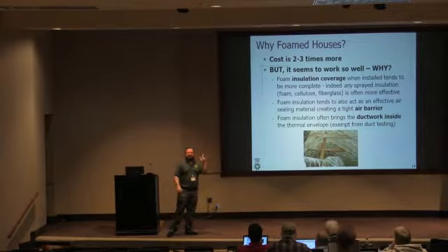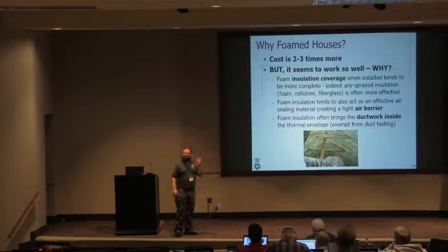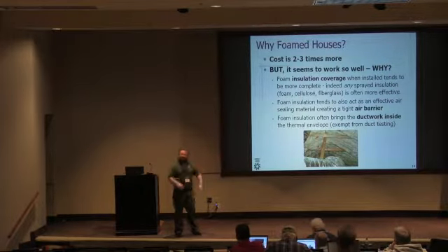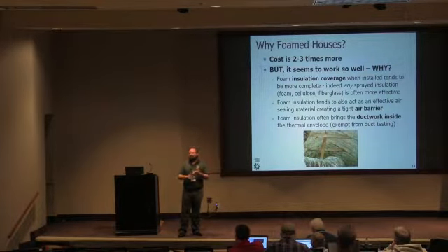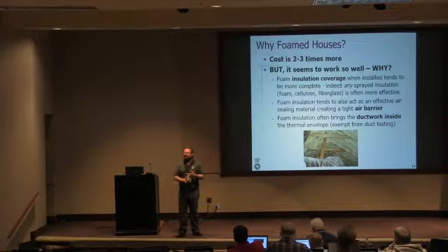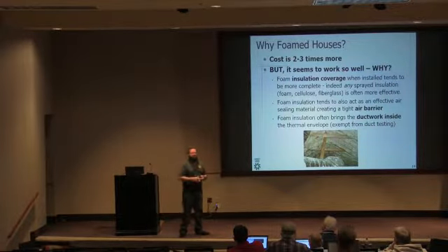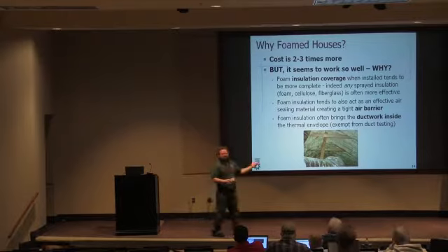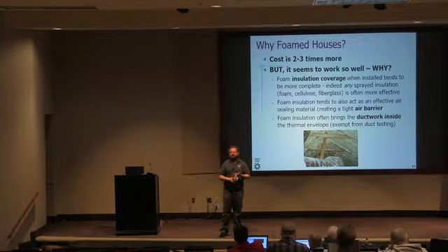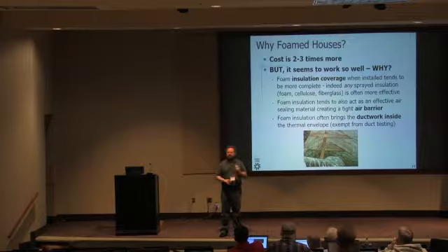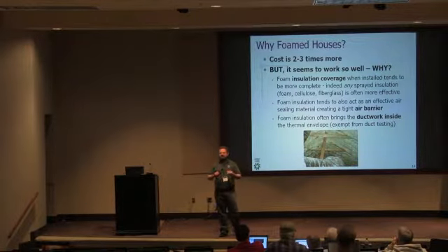Nobody puts in high efficacy lighting, and ducts, especially ducts inside foamed roof lines, because they're not required by the code to be tested, don't get mechanically air sealed. And so we saw 20-30% leakage on duct systems inside spray foam houses because the word's on the street: you don't have to do a test, don't spend the labor and the materials to air seal this duct system. But it's still required by the mechanical code. So those were the three big things we found.